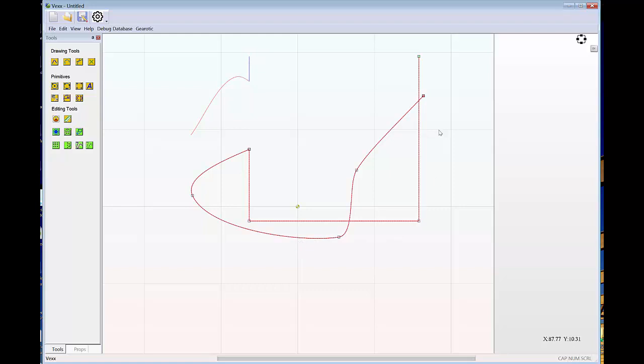Similarly over here, when I select, you can see we have a start point which is green on this particular contour, and it runs through the entire contour to the end, to this red point. It automatically joins things together as you trim and as you cut them. When it fails to do that, you can always pick up a node and move it, because we're in node editing mode.